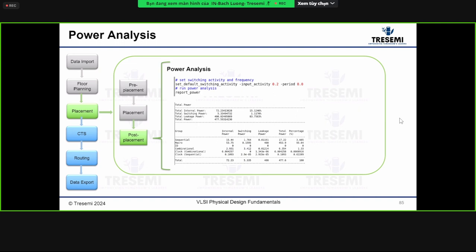But the most accurate one will be running simulation, for example, running a speech processing loop, and setting up everything, and after that you will be able to extract the switching activities on all the nodes, more accurately based on simulations versus based on probabilities.